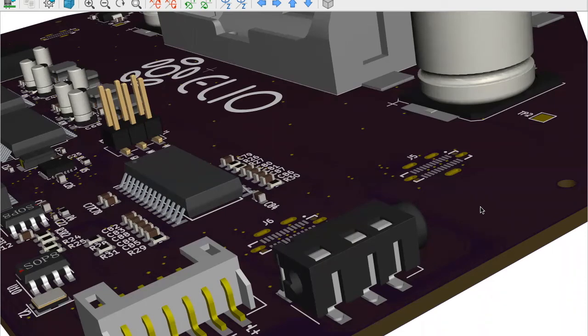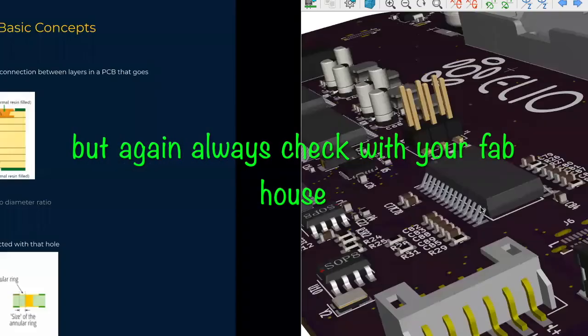Because again, this is dependent on the type of tools that they use, because such vias are actually embedded using lasers. So the strength of the laser cannot go through all those layers. So the maximum you can have is 1 to 3 and 1 to 2. Now say 2 to 3 and 3 to 4. So that again you have those buried vias.